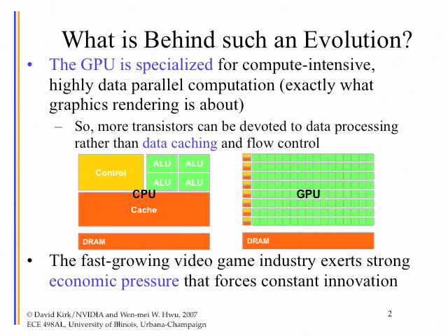So that's called out-of-order execution. Okay, and the CPU will rearrange these instructions because some of these memory accesses will take 5 cycles or 12 cycles to complete, while it would look at some future instructions and see if they can do some busy work waiting for that 5 cycle or 12 cycle latency. All this design costs transistors. Okay, so that's why on a comparable chip you will see a small number of CPU cores, because each CPU core requires all this logic.